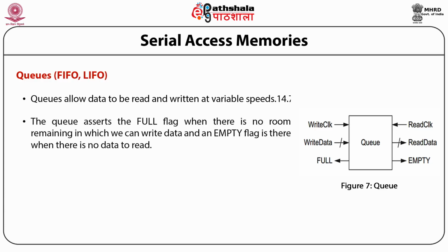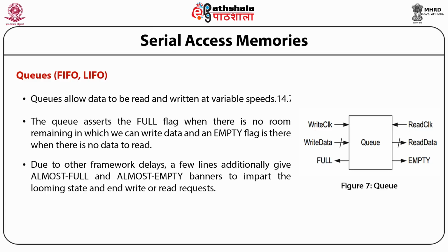The queue asserts the full flag when there is no room remaining in which we can write the data, and an empty flag when there is no data to read. Due to other framework delays, a few lines additionally give almost full and almost empty flags to indicate the looming state and end write or read requests.